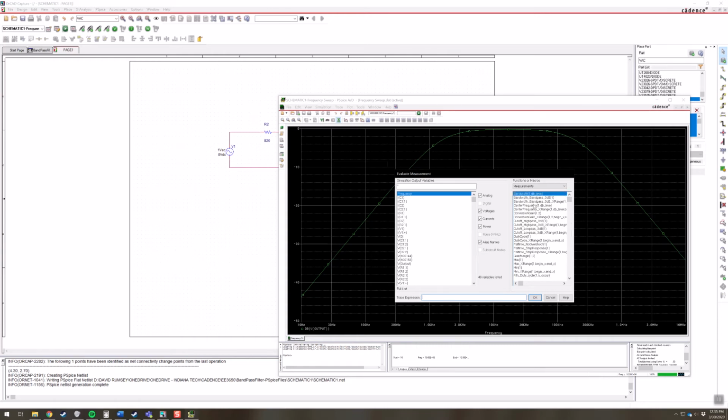So I don't really need to use the center frequency thing anyway, because I can get the bandwidth of the bandpass filter, and then I can get the quality factor of the bandpass filter, and then I can just get it from there. But let's go ahead and just do the bandwidth. The bandwidth here, the dB level we'll talk about here.